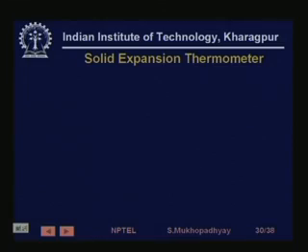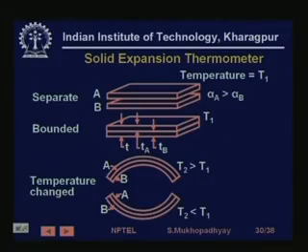So, these are based on the expansion of solid, liquid, gas under temperature principle. The liquid expansion thermometer is the most common, so we told that first. Then you have solid expansion thermometers, which are basically bimetallic strips. So, this depends on the fact that the expansion coefficients of the two solids are actually different.